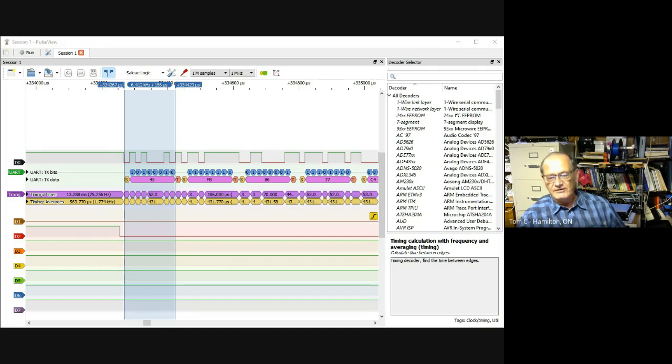And that's when I discovered that the third-party person who wrote the code I'm using, this very fast software UART, had elected to turn off the pull-ups in the digital output pin that this thing drives. As a result, there was no pull-up. He just assumed everybody had pull-ups on their outputs. And I added one and I solved the problem.